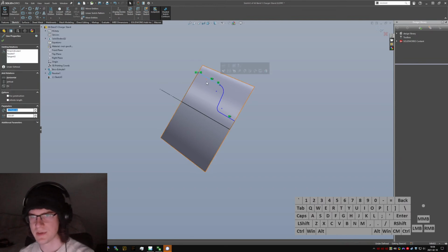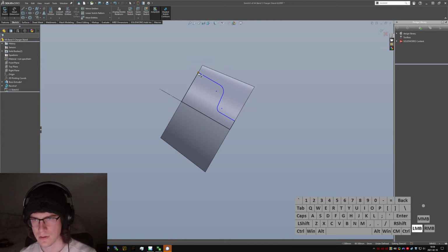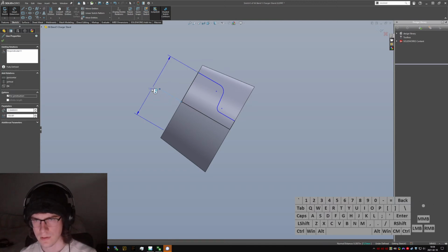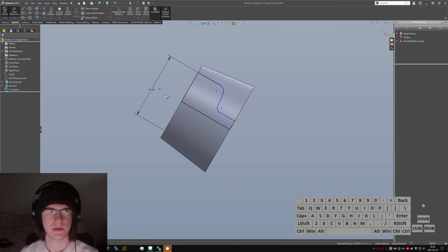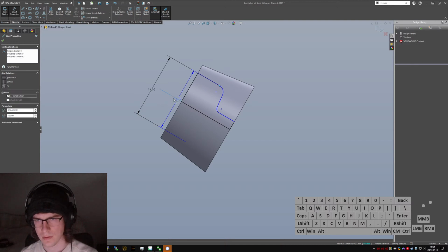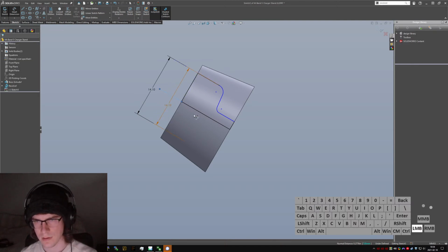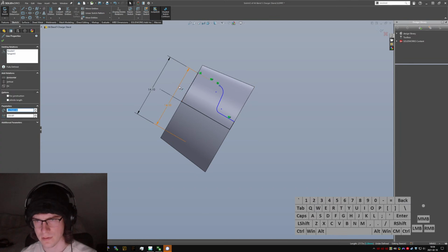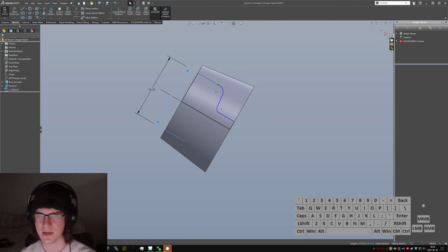Okay, so this guy mistakenly grabbed, I think, perpendicular to that, which I don't want. I think I'm just going to have to use an offset edge or something, because otherwise I will never be able to correctly grab. Why is that driven? You should be driven. Oh, it's because I selected the edge for this first one, which would enforce parallelism there. Not what I want.